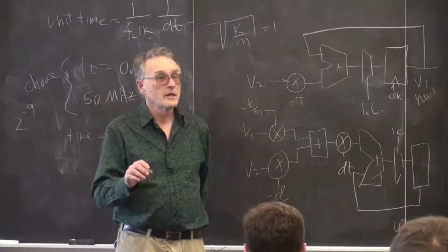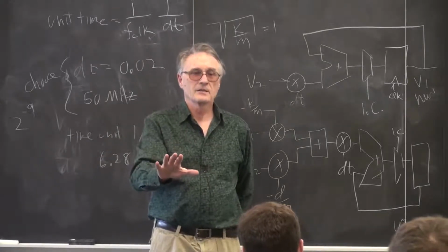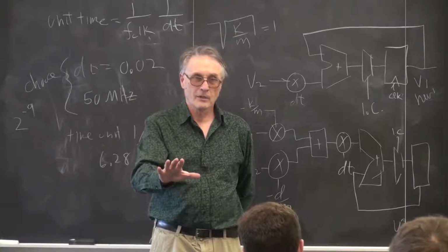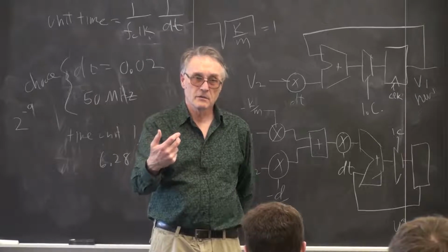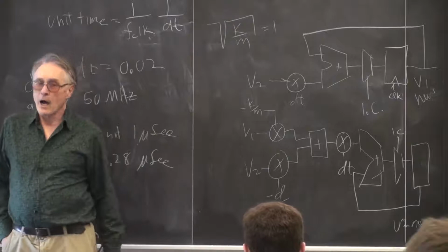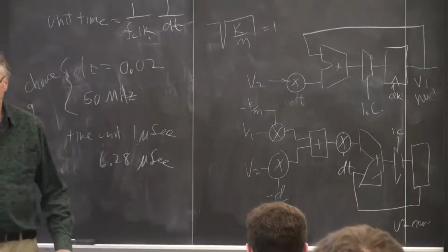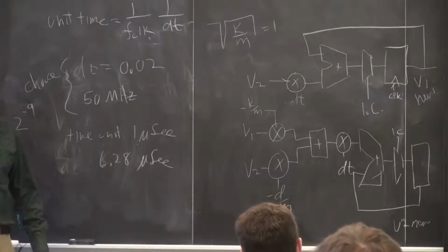For instance, in some cases, if you multiply by any constant, it doesn't make a hardware multiplier. It just instantiates a bunch of adders. I would use a shifter to make sure that it's not instantiating a multiplier.